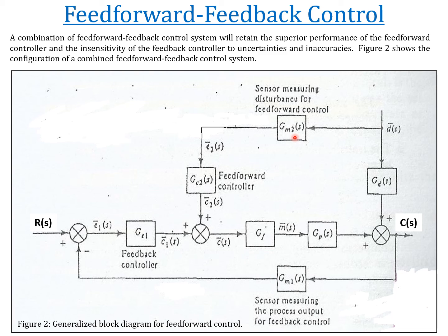We have other slight changes in the dead time compensation technique. We have a few other minimal methods that are not common. I'm not covering them here, but you can see in the books some of the methods, not so popular in the real world. But these are the main ones: cascade, ratio, and feedforward, that are most popular among the classical advanced control methods.